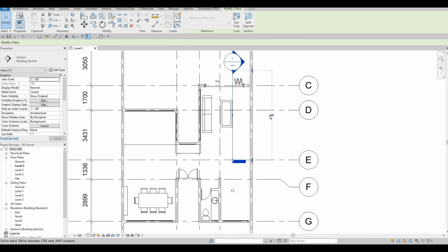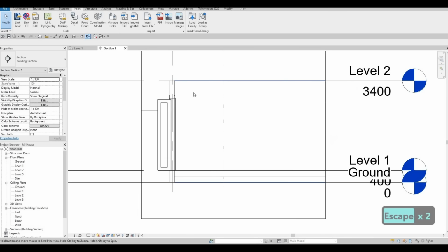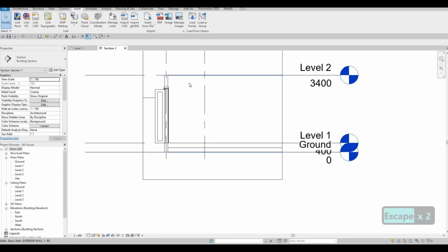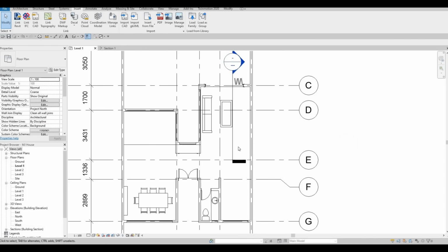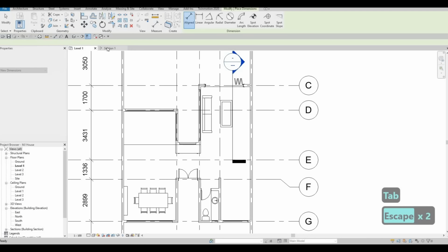This is the range that you can adjust by dragging the arrow. For now, this is good enough. If we double click here, you'll be able to see the wall that you have right here. I'm just looking at it, I want it from here to right here, so around 3850.